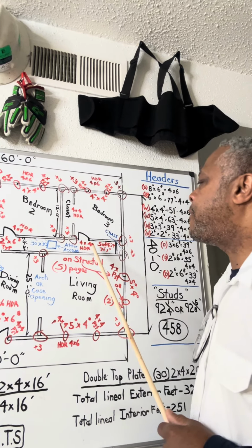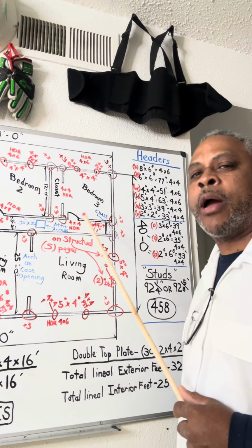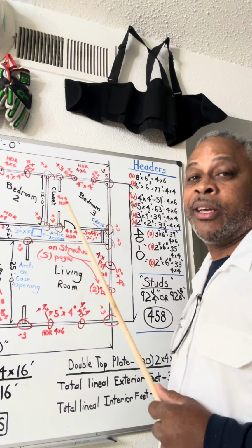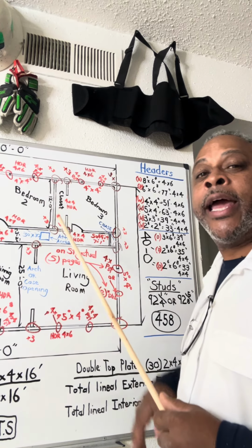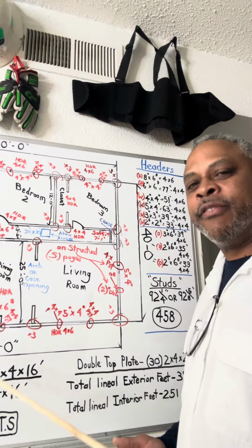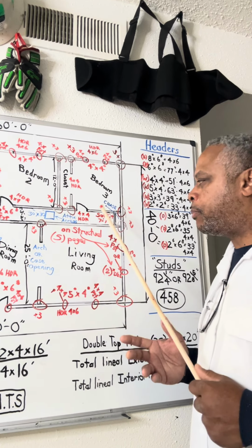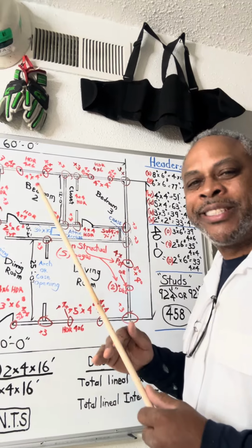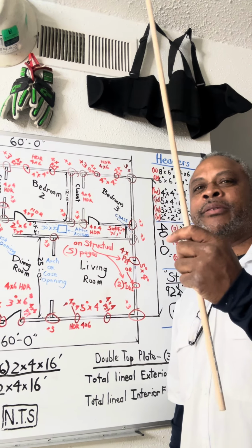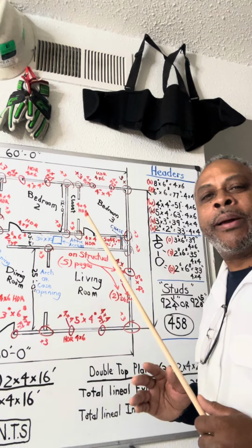I have a 7'1" soffit. That is the framing height. Because when you put your drywall at 5/8, it's going to at least come down to 7 3/8 of an inch as your finish, along with your carpet or your tile on your floor, 7 foot even. Okay, we want 7 foot. That soffit has to be framed along. It's a drop ceiling, we call it. It's not the standard height of a regular ceiling like you see up above here. It drops down because it services a lot of your mechanical trades.